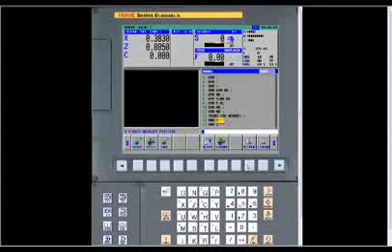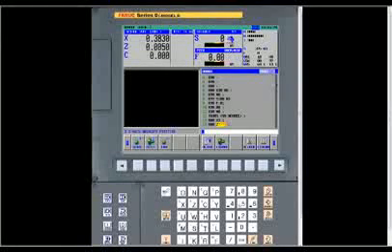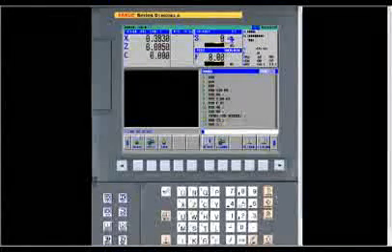And, you know, like Programming 101, typically you would go 100 thousandths above your stock and 100 thousandths in front. That's what I always do. X 3.1, then alter, just like before. Put the cursor over what you want to change, and then 0.1, alter again. So now we've called up the tool. We're at a clear position.